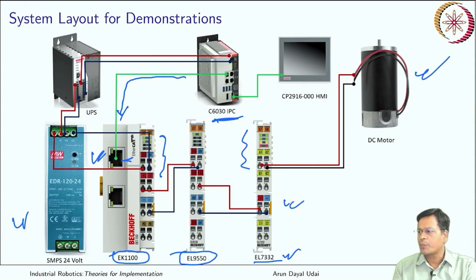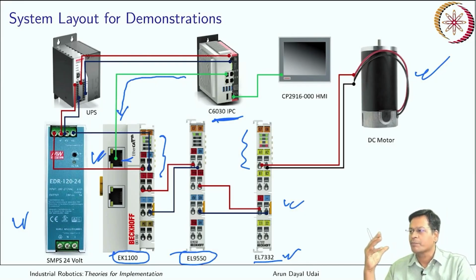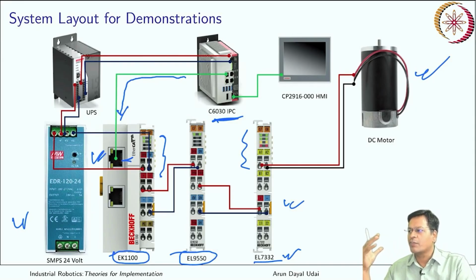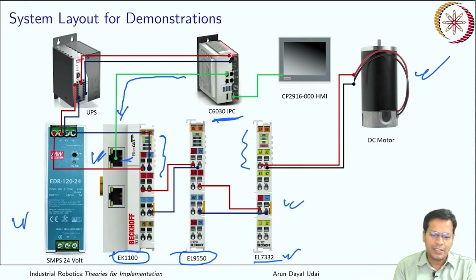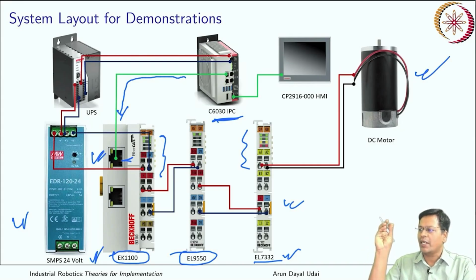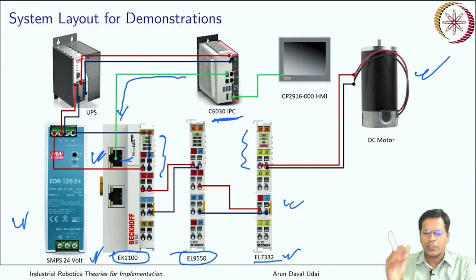Okay, I hope you got this system, right? Let me just repeat: you have a program. You also have a software layer, TwinCAT, where you define all the process variables. TwinCAT is a real-time IO system that can communicate with whatever external devices are there. It can take in data, it can feed in data, right? And finally, it can make variables accessible to the other programming environment. Over here, this programming environment is Python. So that is what is changing the process variable.